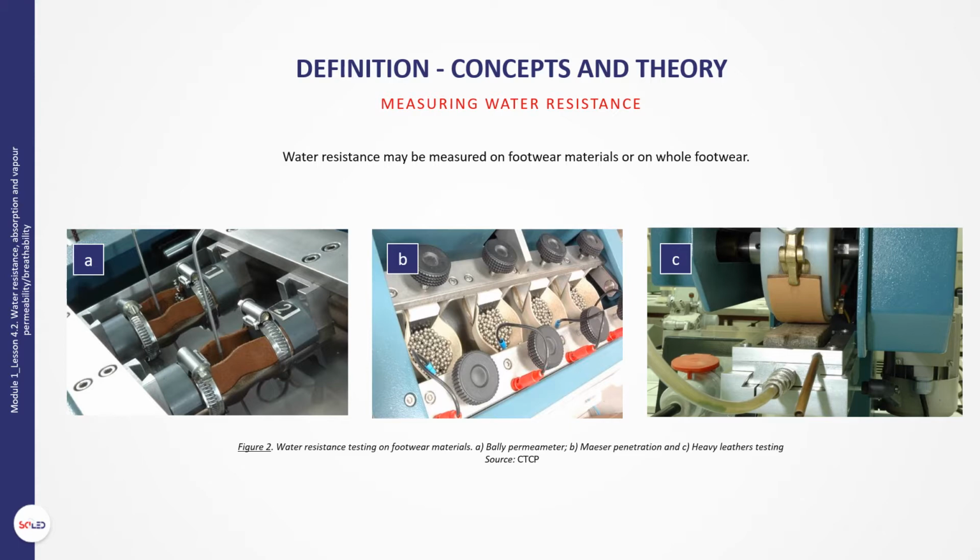The methods also allow the percentage mass of water absorbed and the mass of water transmitted through the test piece to be determined. The Bally penetrometer testing methods are described in ISO 17702, Footwear, Test Methods for Uppers, Water Resistance and ISO 20344, Personal Protective Footwear, Footwear Test Methods.